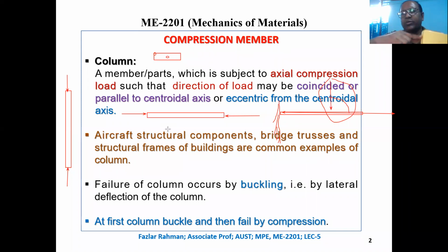So this compressive load is going along longitudinal axis of the body, right? But I can apply over here at the corner. But still, direction of load is parallel to the longitudinal axis of the body. So this load, instead of applying at the center, if we apply at the corner, that is called eccentric load.